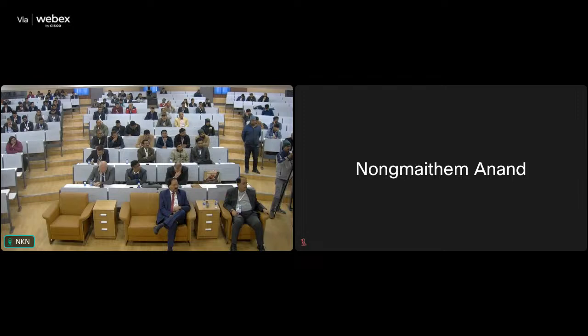So once your Q is improved, right? And you know that this much is the improvement, then accordingly you can use that Q value in your ground condition prediction criteria, and then you can see how your moderate is going to mild or mild is changing to non-squeezing ground condition. Okay, I think it's clear. Yes, please.